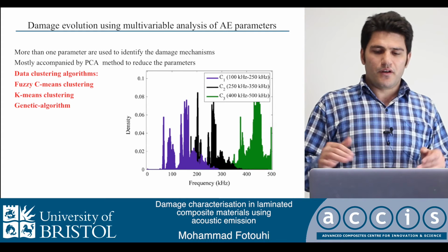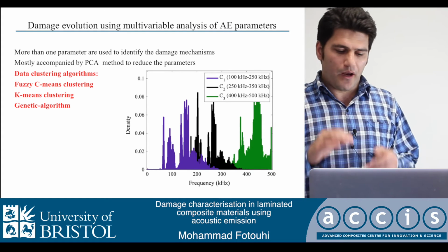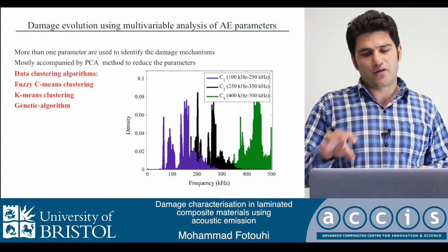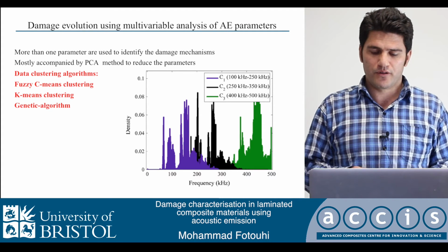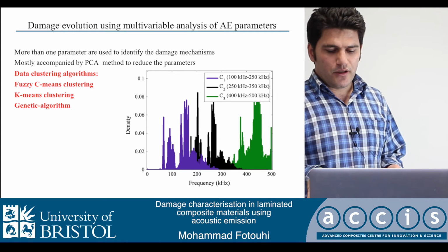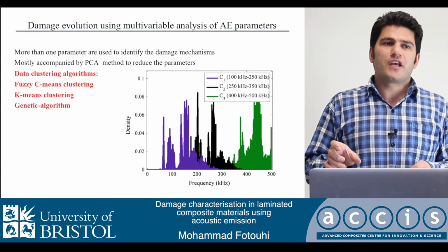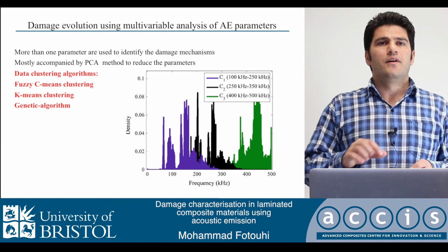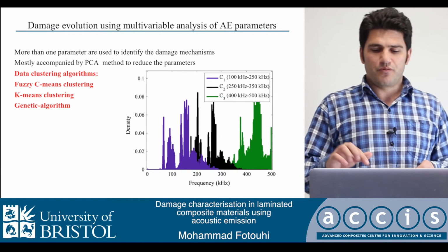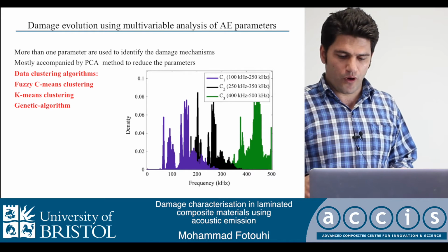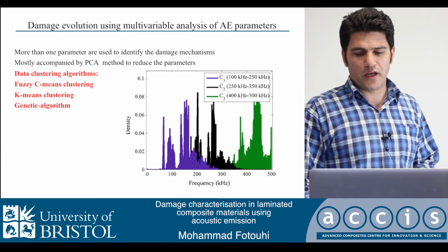And we said that it's okay, we can determine the type of damage mechanisms using analysis of AE signals. As I told before, each type of damage mechanism has its own AE features, which makes it possible for us to determine these damage mechanisms.